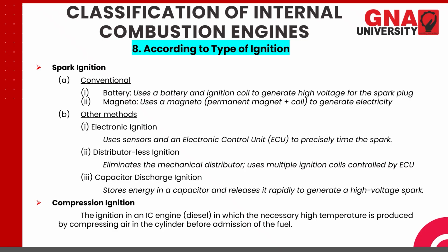Distributor-less ignition is there, wherein the need of mechanical distributor is eliminated. It uses multiple ignition coils controlled by ECU. Then the third one is capacitor discharge ignition.